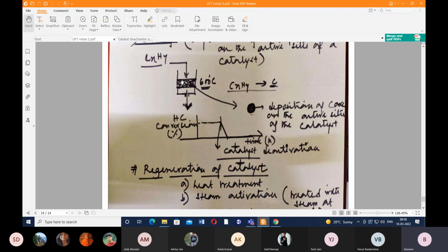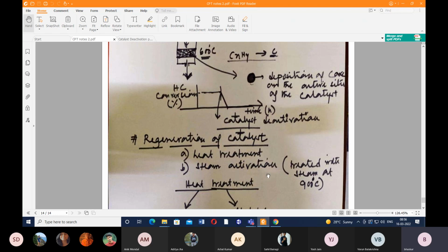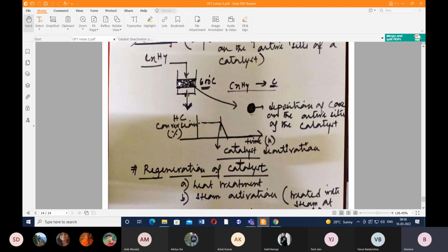And again, when we encounter the same coking issue, the same treatment will follow. Again, we'll recycle it, meaning recycling would be performed several times to get rid of the coke deposition or coking issue. When we have a coking issue, we have no productivity as such. So in order to enhance the productivity, we will again have to do the regeneration operation.